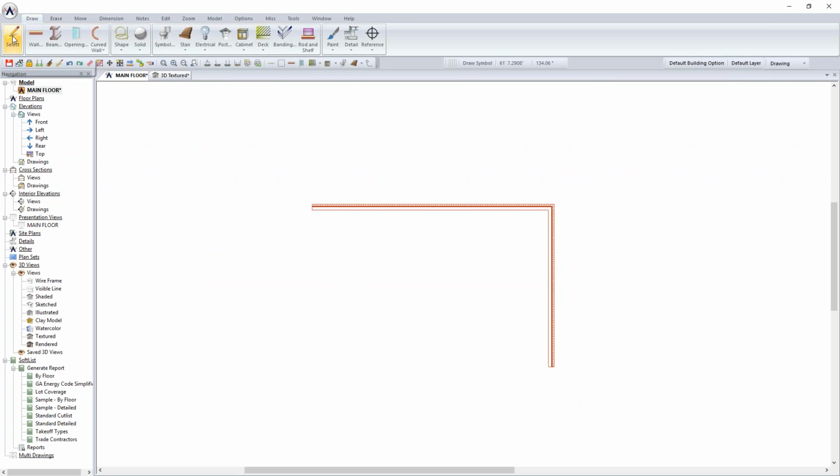So in this case, I could select Draw Select. And one of the things that I want to point out to you as I hover over the ribbon bar is many of the commonly used commands are going to have a shortcut set up for them. So you can see that the tooltip tells you Draw Select, draw item to, or select item to draw, but it also has the letter S located under it. And the letter S acts as a shortcut to that item.